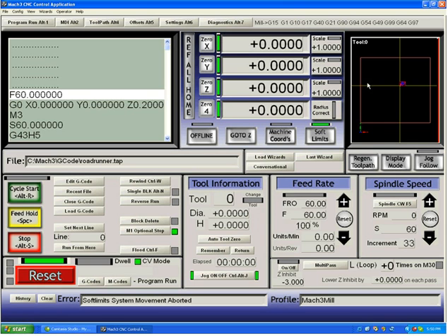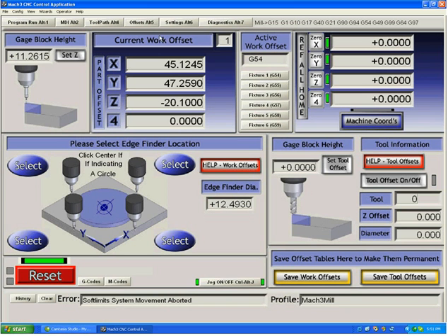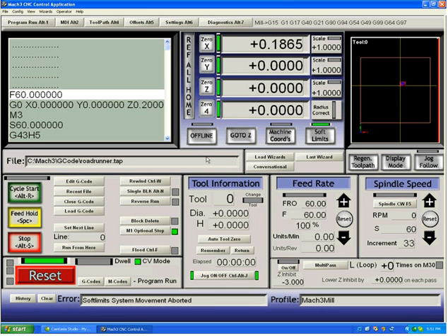So, with that having been said, I think you understand a bit more about home switches, how to activate them, when they should be active high and low, and what all of it means when you select an offset system. And remember the most important rule of all. If you set a fixture offset because you have a jig attached to your table, or you know that at 50/50 minus 20 will be the top part of a piece of material you're going to cut 1,000 times, never press the 0 buttons once you're in those fixtures. Always go back to fixture offset number 1 if you're going to jog around and do jobs at an indiscriminate point simply by hitting 0